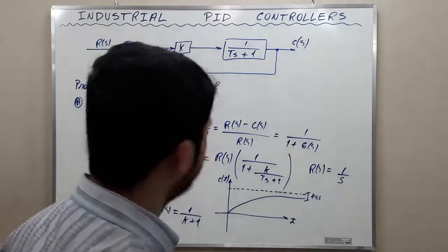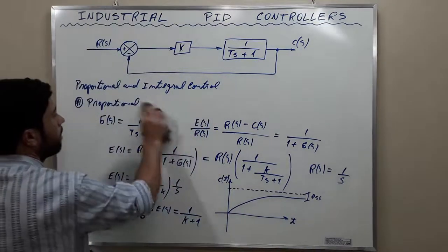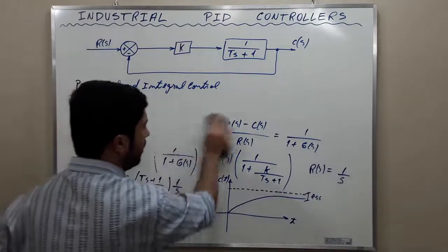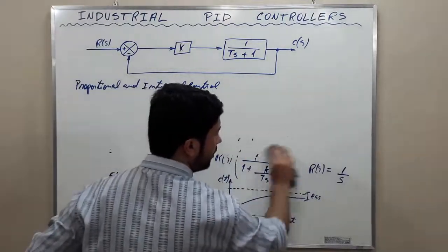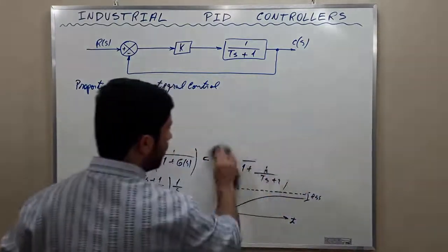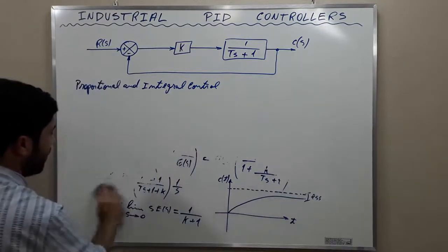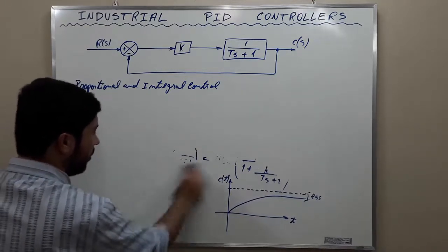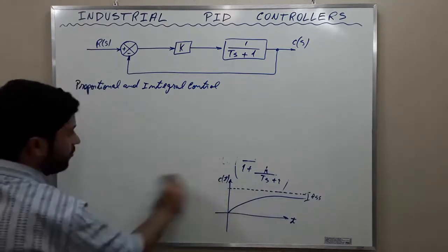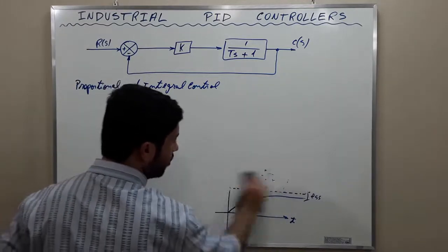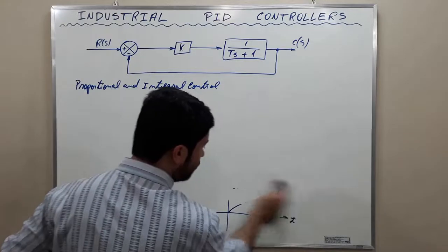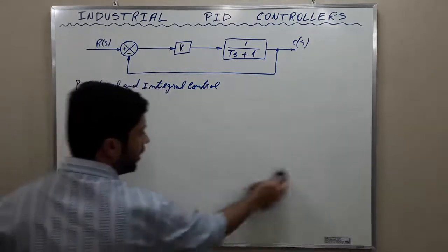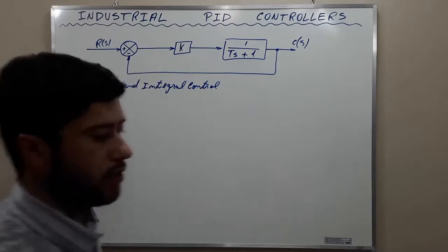Now let's analyze the integral control, which is going to be letter B here, and how to reduce this error, because we want to compare the output signal with the reference input. When the reference input is the unit step input, we wish the output to be equal to 1. But if there is an error, the system is never going to be fully controlled. We need an integrator to be able to reduce the actuating error signal to 0. So the system will reach steady state.